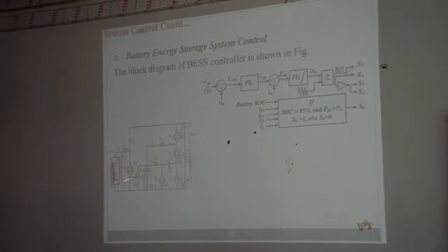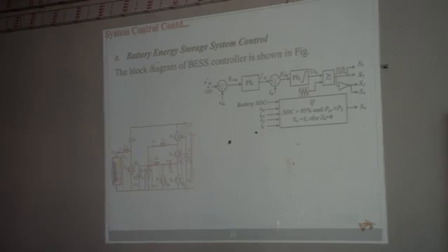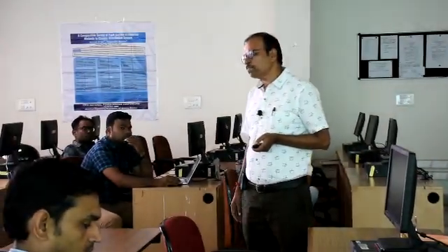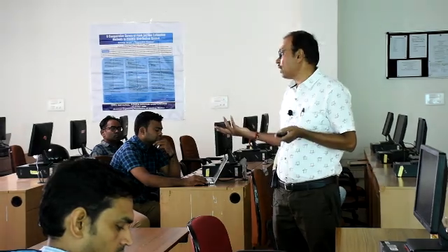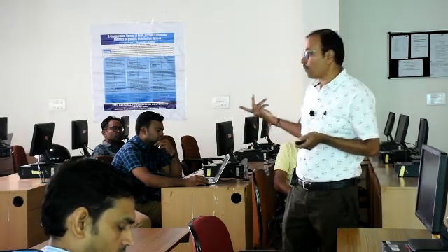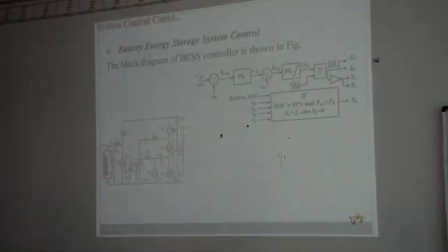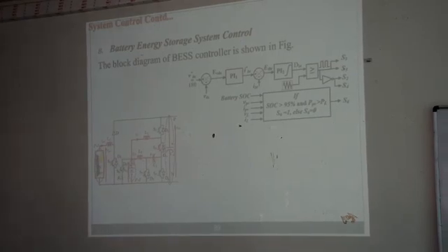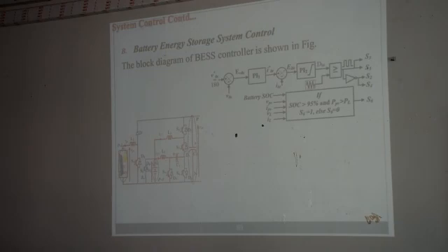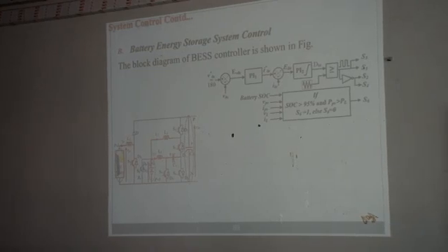Now the switching of this switch depends on the external cases. You may have the case when the battery is fully charged, generation is more, and the load is not demanding the power, then your system will destabilize. So you have to take care of this also. So basically you will switch this switch only when the battery is fully charged, meaning the charging level is more than the satisfied charging level, and the power generation is more. So you may have 2 options in this case.